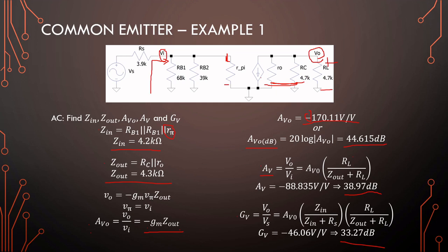So with the change in temperature, our input impedance can change, and same with our gain. If temperature dependency is not eliminated, even our gain can change over time. So this amplifier you will typically see when you switch it on, after a while, the gain will start to drop.